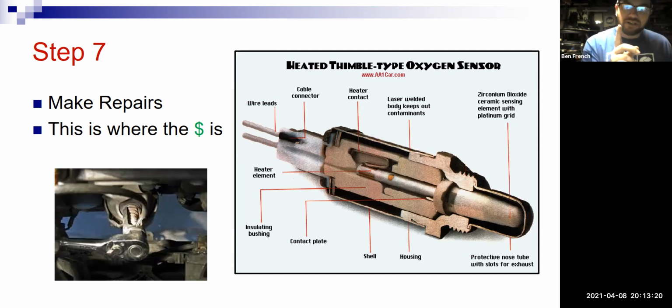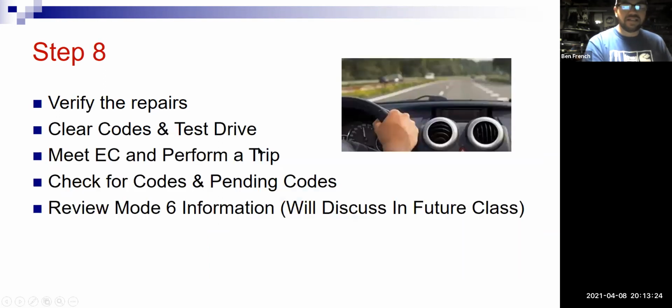You're not done though, because remember, step eight is always verify the repairs, right? Go for that test drive. But it's not just a generic test drive. You're going to drive it in such a way that you meet the enable criteria and you perform a trip.